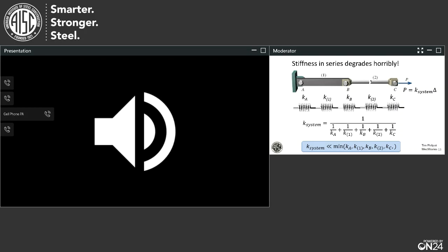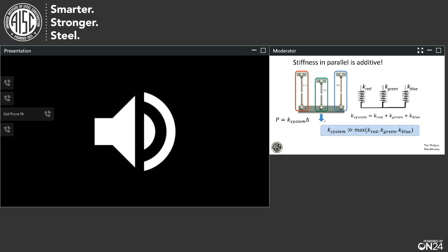They're acting together. Each one is taking on some of the lateral load to resist the force. So that example that the person laid out, I see where the confusion is. They're side by side. They feel like they're in series, but in reality, they're in parallel. Each one is intending to do some work in resisting the lateral system.